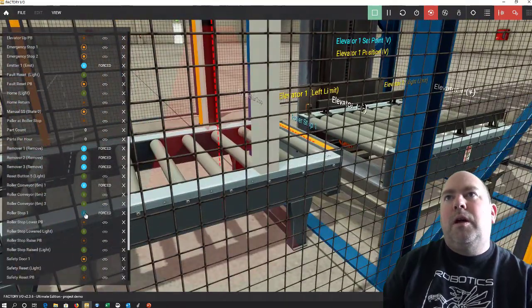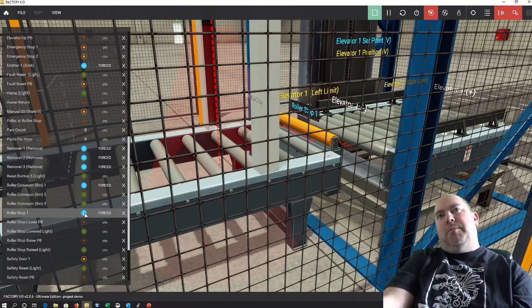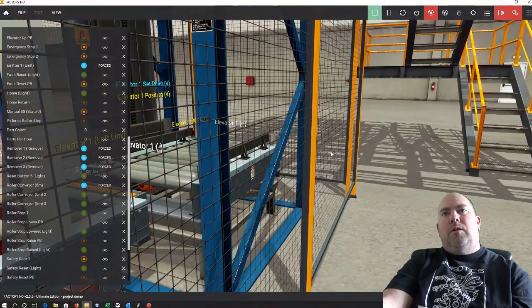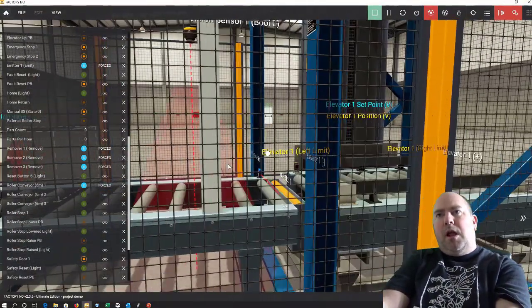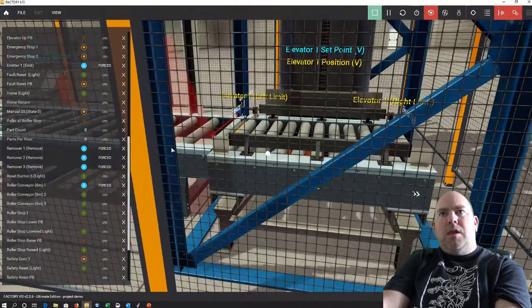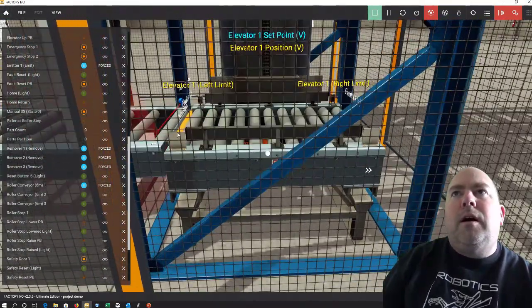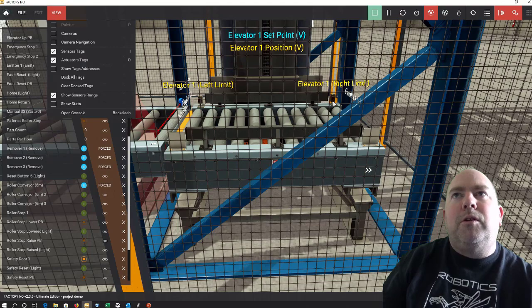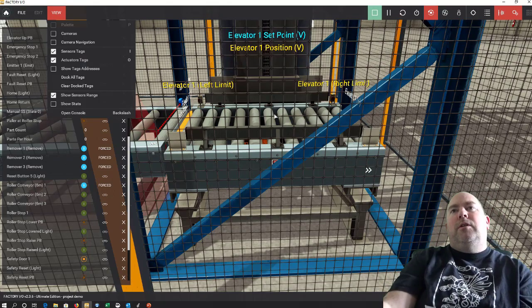So roller stop will basically, pallet comes up there, roller stop will drop down. Then we roll in here. Once we are on that photo eye right there, so once we're on that eye, let's see that we're on that one. We'll see that we're on this one. Once we make this one, we're going to say that we have loaded the elevator successfully.